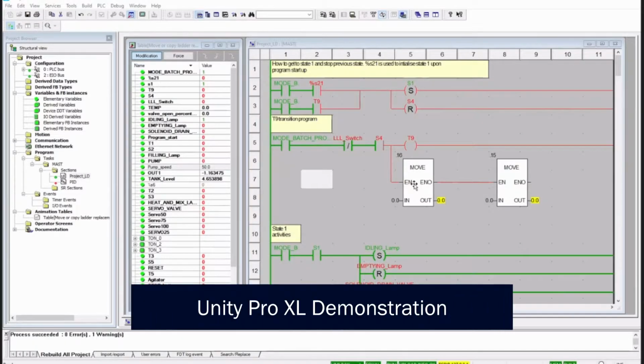The communication between these two packages is usually through Modbus, sometimes DeviceNet, sometimes Ethernet IP, DNP3. It really depends on the client's requirements. And then as control system design engineers, we would recommend some communication protocol based on the client's requirements. So let's have a look in detail at a real-life example of how we use UnityPro to integrate into the CitectSCADA. To program the PLC, we're using UnityPro.